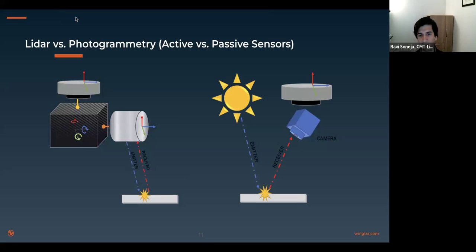So talking about LiDAR, which stands for light detection and ranging, it's using a pulsed laser in combination with a scanning mechanism. Generally, that's a mirror that's either rotating or oscillating inside of the scanner head. And these are active sampling systems which generate their own source of energy. For that reason, it is agnostic as to when you can collect it. You can collect LiDAR day or night.